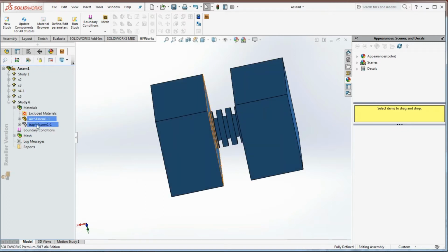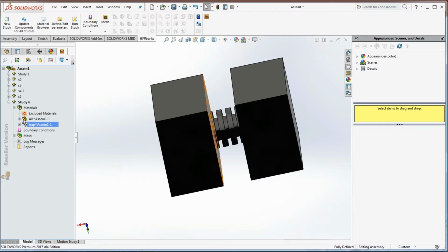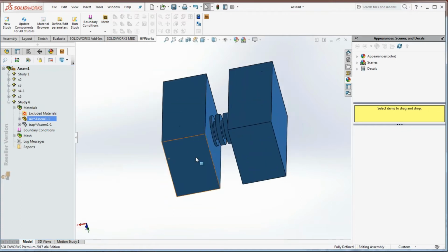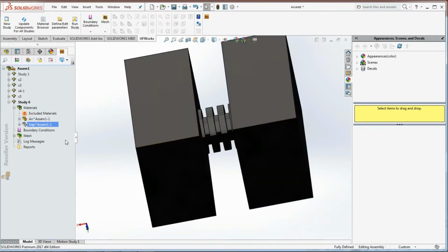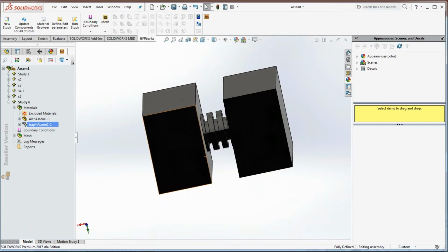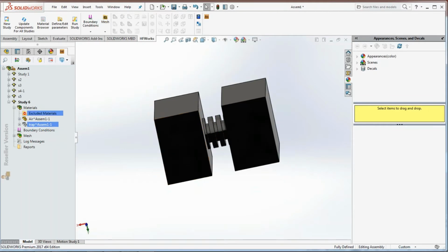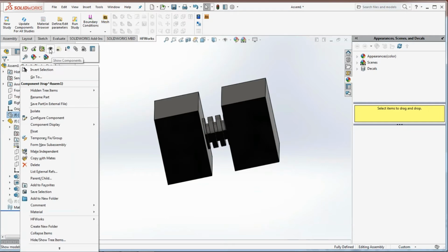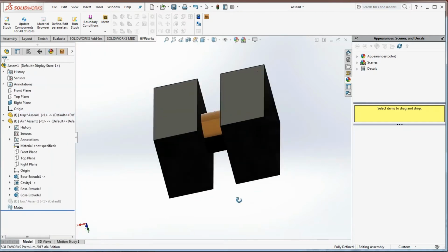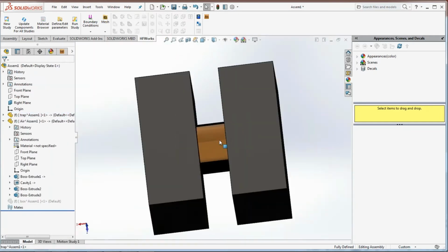I have two bodies, like 2 parts. One part is the air that I created just to mesh and model. The other part is the RF trap itself, like I called RF trap here, is the filter. So you can come here because I hid it, so you can show it again. This is our filter, right?